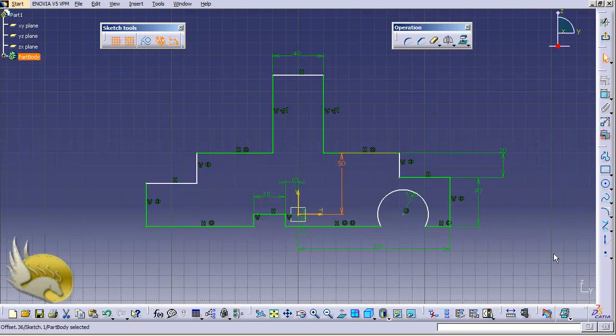Most of my shape has turned green. Now I need more constraints. So this is symmetry. I have the symmetry. I need to click on the constraint tool, select this line, and now clicking on the horizontal line, you can see that this is over defining. So I press Ctrl Z. What I need more is actually this line, pressing the Ctrl button on this line, and I want to have symmetry between these two.